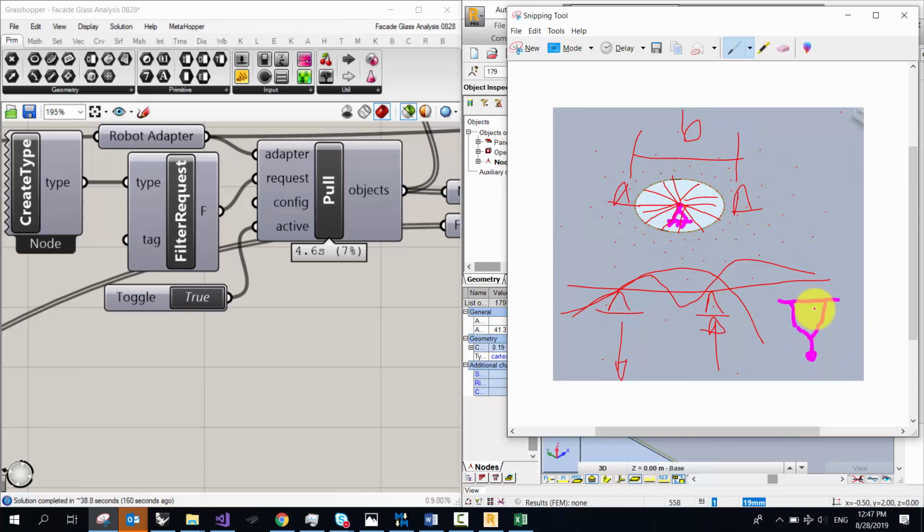So if we want to see this panel pivoting about this point right here, which would be on this image, we have to give it analytically one pin and nothing else. Make it such that it does do that. Either way, as you say, it's very close. And what we noticed was that would probably be another way of doing it, but could you imagine having to do this every time? Click, click, click, click, apply rigid link, master nodes, slave nodes.